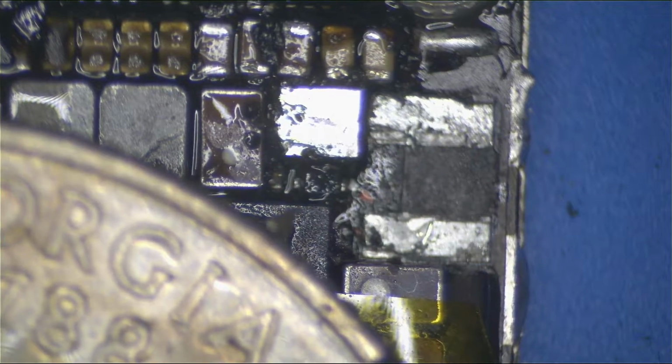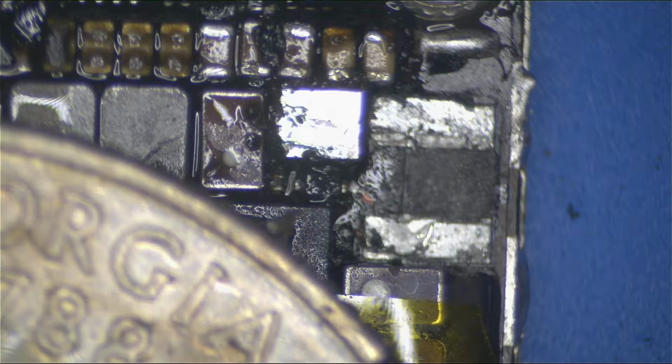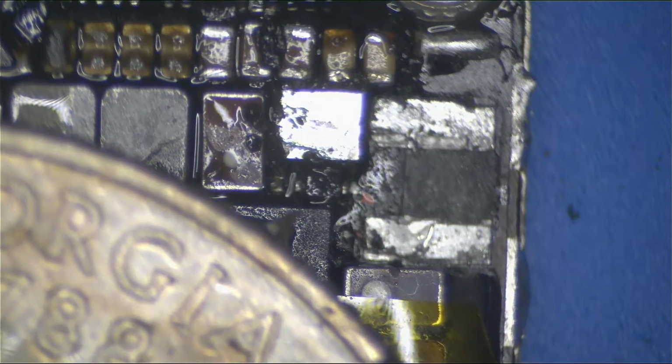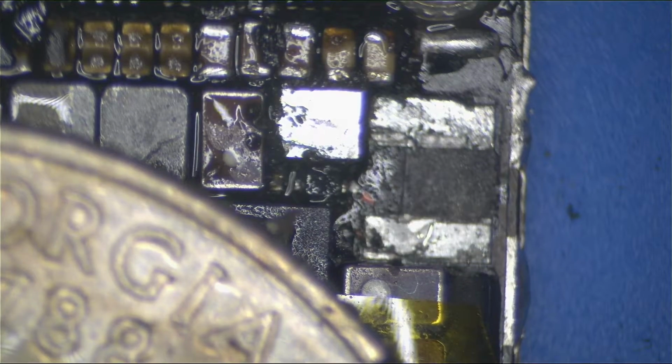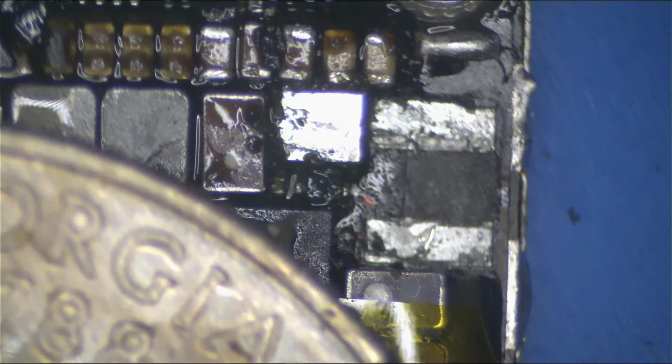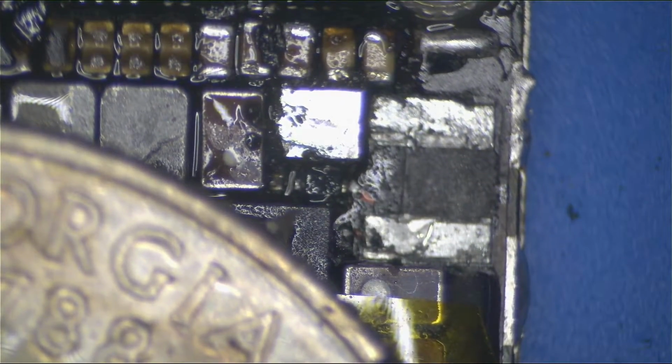And what you do, it's really cool. You take a blob of solder, stick it on your tip, and then just touch the top of the IC, and the heat will transfer through the IC to the balls, and just completely pop that chip off without any hot air and without damaging anything around it. Now, this will completely ruin the chip, but we're not going to be using that chip anyway, so it doesn't really matter. So only use this trick if it's a chip that you don't want to use again.